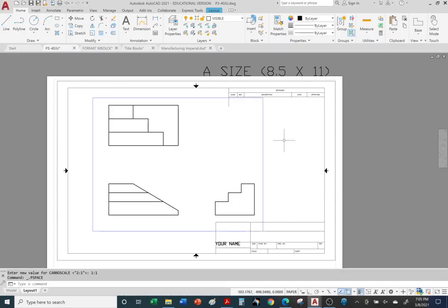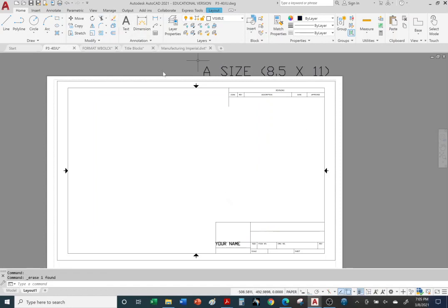Okay, one thing that may happen is you may accidentally delete your own viewport. Okay, so it may happen, right? You accidentally delete the viewport. It's like your phone is not charged, right? You try and turn on your phone, you forgot to charge it, battery went down to 0. You got to charge it, right? In this case, we can go ahead and insert our own viewport.